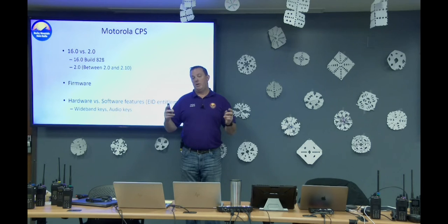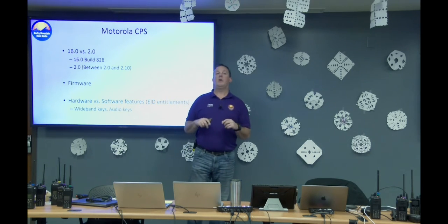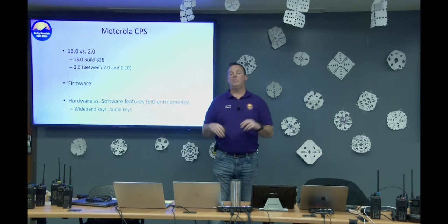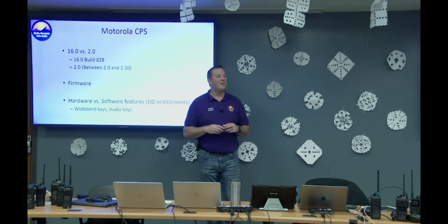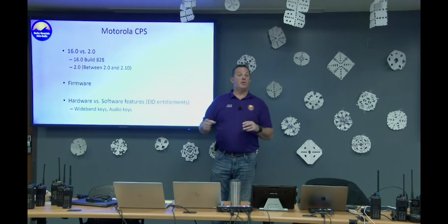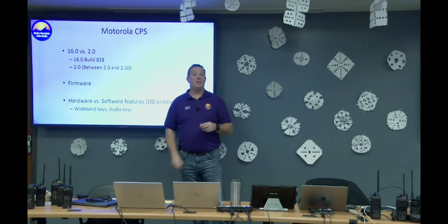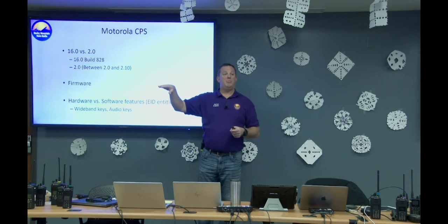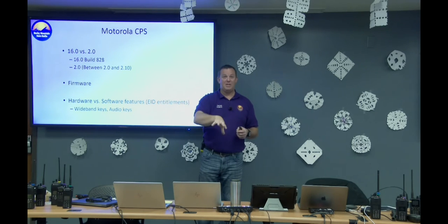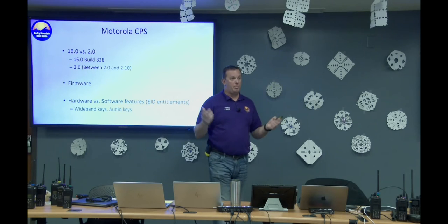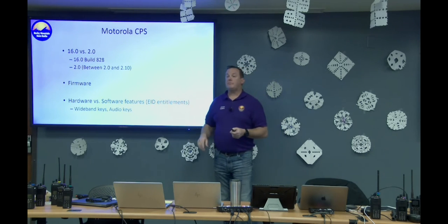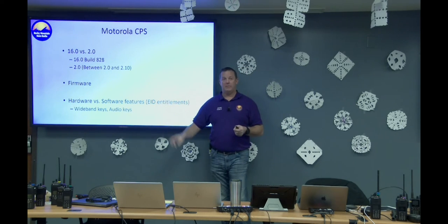So as a Motorola customer, we can go in and take a little course. It's really watching a video. Once we have completed that 15-minute video, it says we promise not to do anything bad and operate wideband in commercial areas, et cetera. You are certified to download wideband entitlement keys. You install that in your CPS, and from that point, that CPS on that computer can program wideband into any radio. Wideband entitlement keys are free.